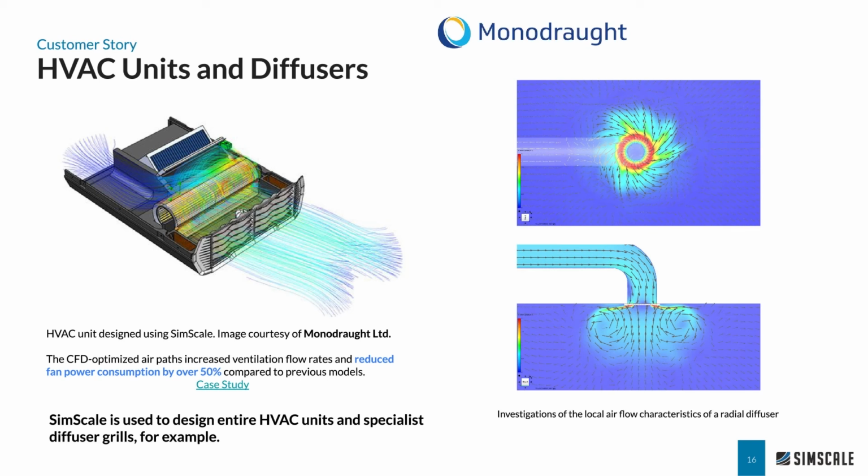and get the detailed flow patterns, for example, for this swirl diffuser here. You could also then export the flow behavior from a detailed model and use it as a boundary condition in a larger room, right? If you have a large atrium, you don't want to model all these diffusers in detail, but rather the effect of those. And that's typically how we do it: we define a specific custom boundary condition that mimics the behavior of this diffuser without resolving all the details in a large space.